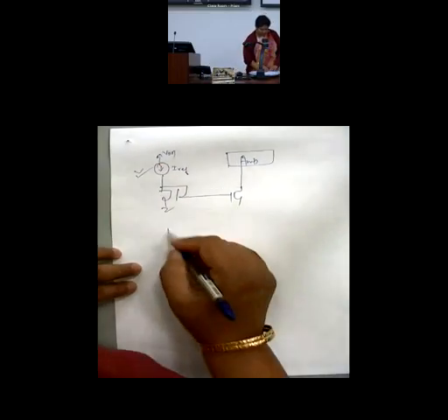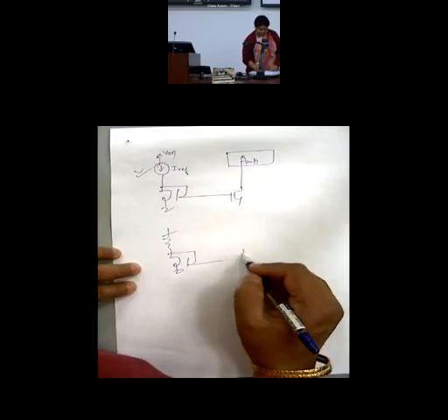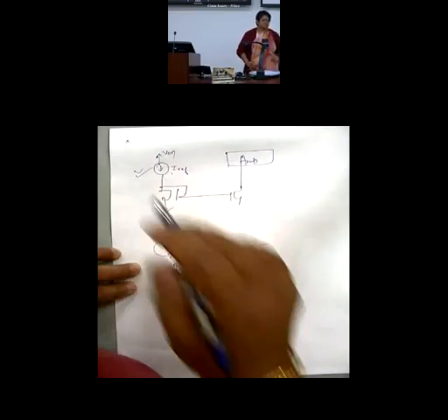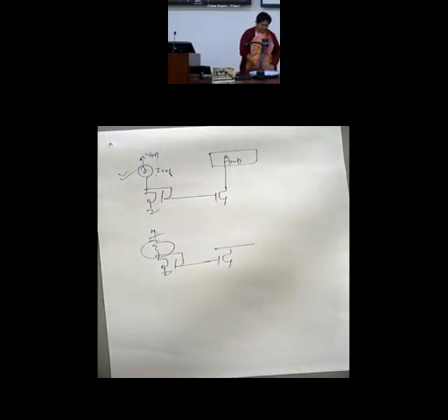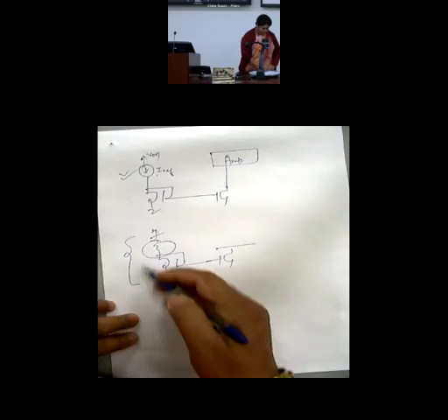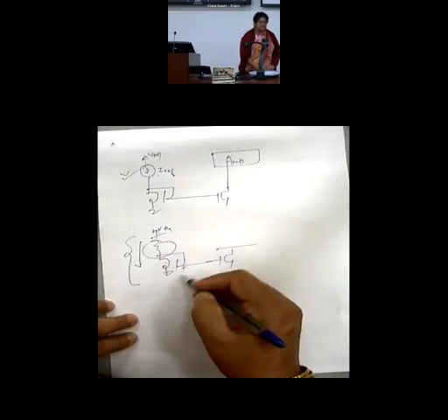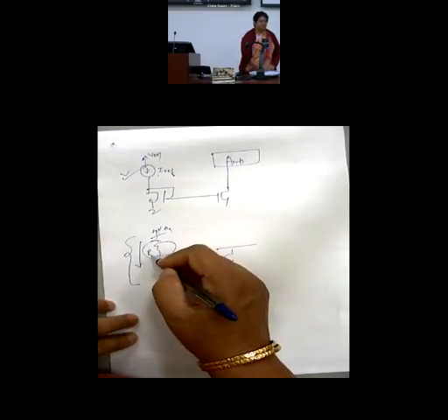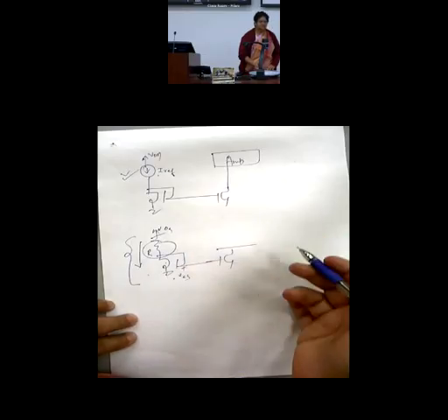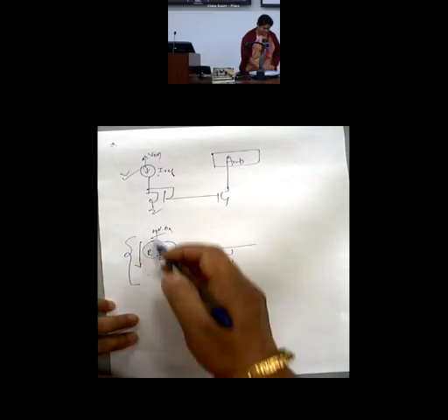Initially we used to show the circuitry with a resistor. Gradually I started changing this resistor to IREF, just to show you the concept of IREF, that IREF means generating a current in this arm. How to generate this current? Very simple. VDD minus VGS divided by R will give you the current. So current is known, VGS you choose, and accordingly set the W by L. Designing a reference arm is very easy, but we do not use resistance.